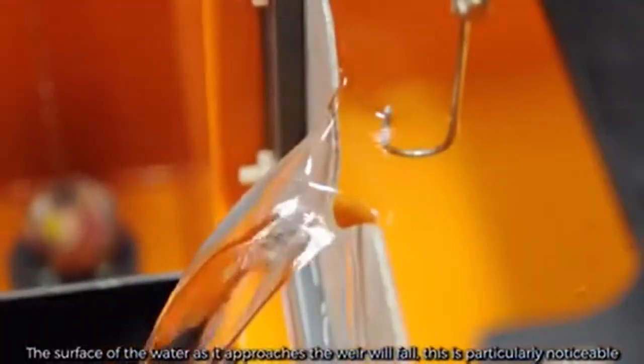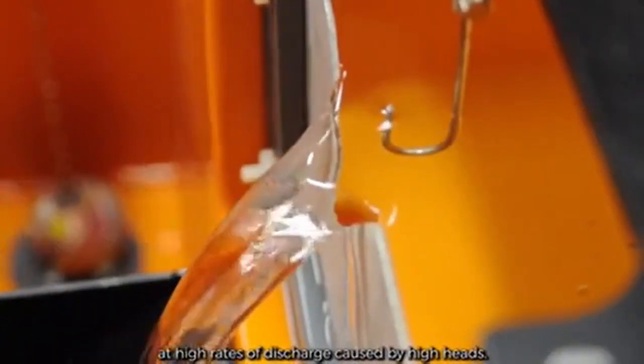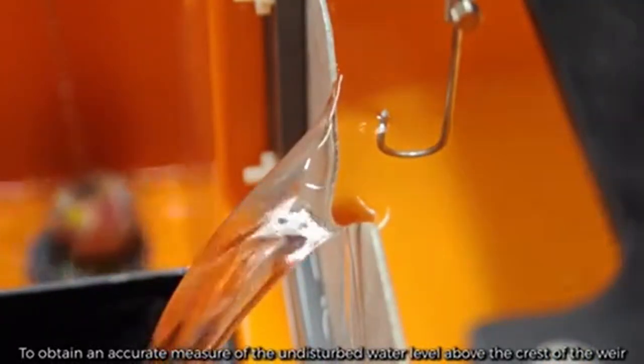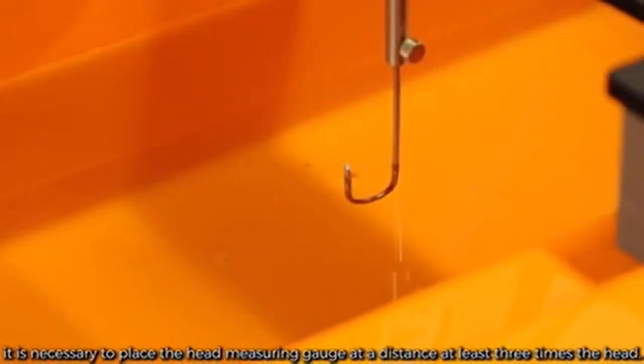The surface of the water as it approaches the weir will fall. This is particularly noticeable at high rates of discharge caused by high heads. To obtain an accurate measure of the undisturbed water level above the crest of the weir, it is necessary to place the head measuring gauge at a distance of at least 3 times the head.